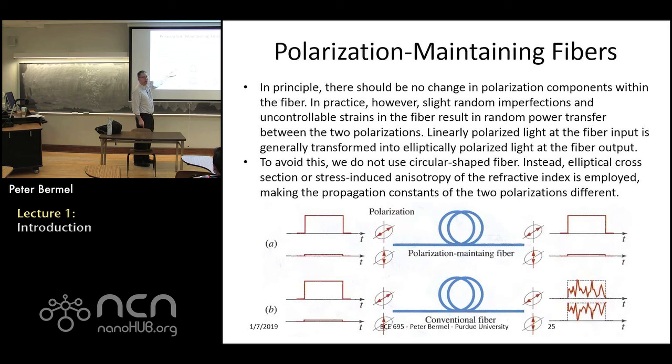So now instead of having two HE11 modes, we really only have one HE11 mode at a given wavelength, and then we have another HE11 mode at a slightly different wavelength. Now you can more easily distinguish between the two of them. That's the real trick to getting a single mode fiber, right? You not only have to have a small enough V number, but also a slight distortion of some sort, like ellipticity.